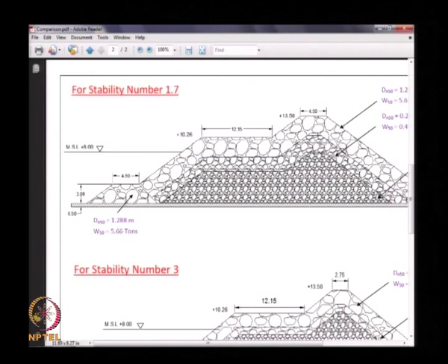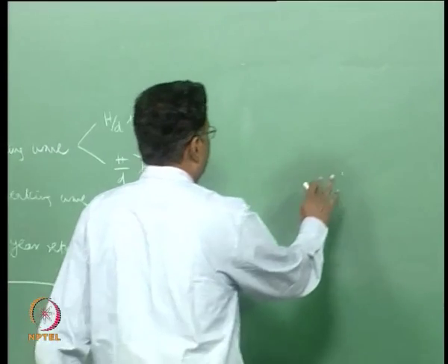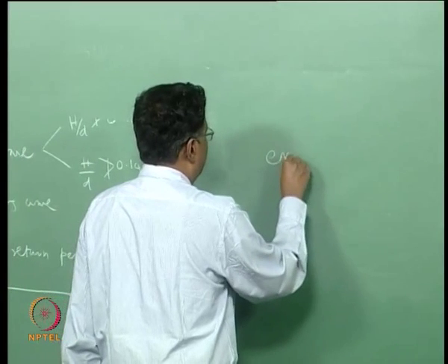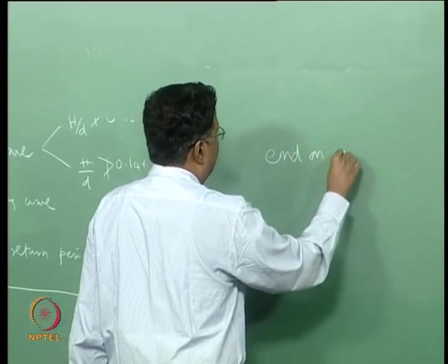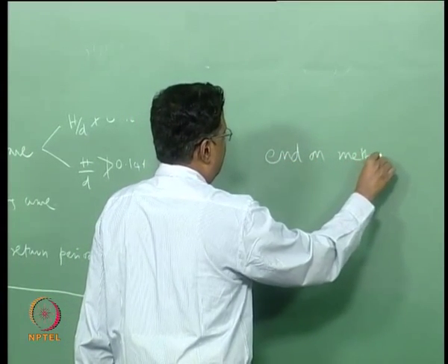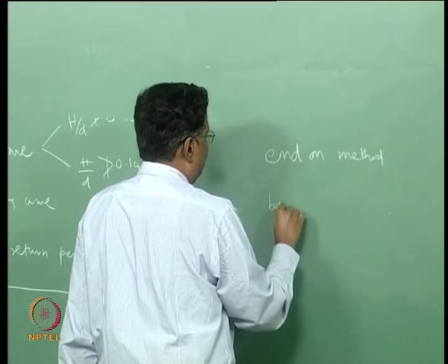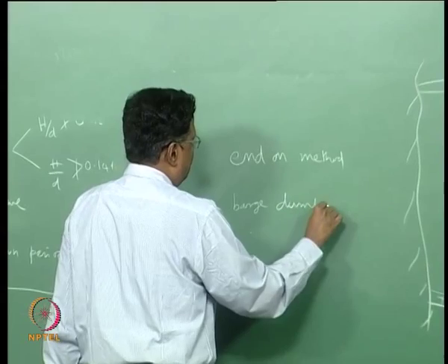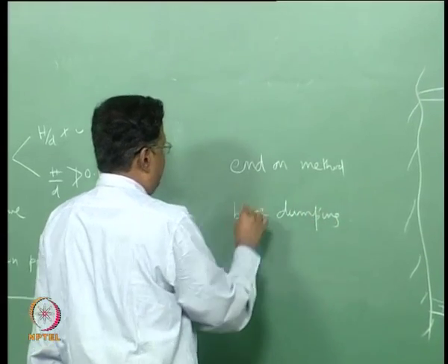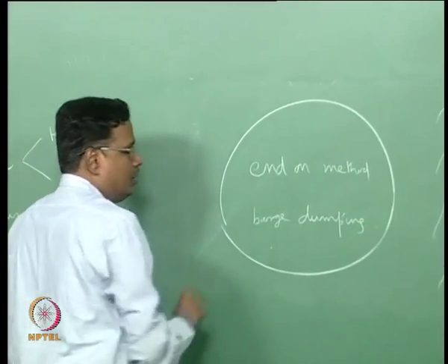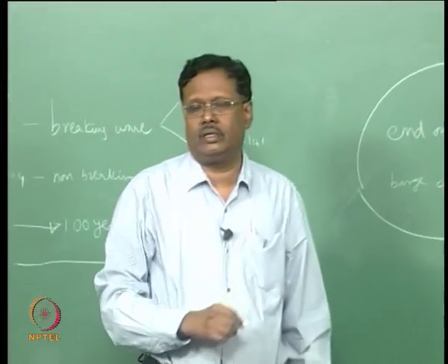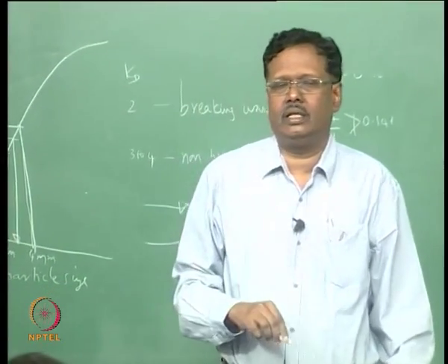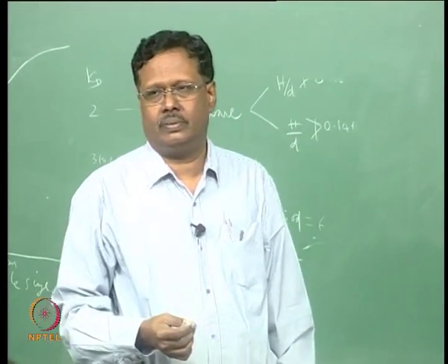There are other methods also to construct the breakwater. One is called the end-on construction, the end-on method. Another is by barge dumping. Sometimes a combination of these two will be used, the end-on method as well as the barge dumping.